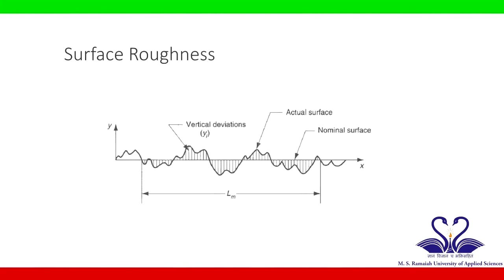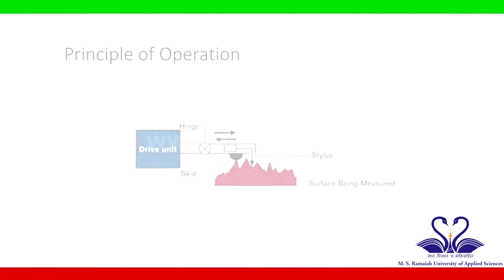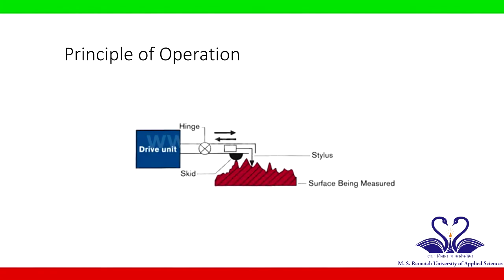Surface roughness is a measurable characteristic based on the roughness deviations on the surface. It is a contact type of measurement, also known as skid type roughness measurement. Here, the specimen surface is placed under the tracing probe. The stylus has a diamond tip that is traced across the test specimen. The stylus with the diamond traces the peaks and valleys on the surface. The mechanical fluctuations of the diamond tip are converted into electrical signals and later filtered to capture the surface roughness.